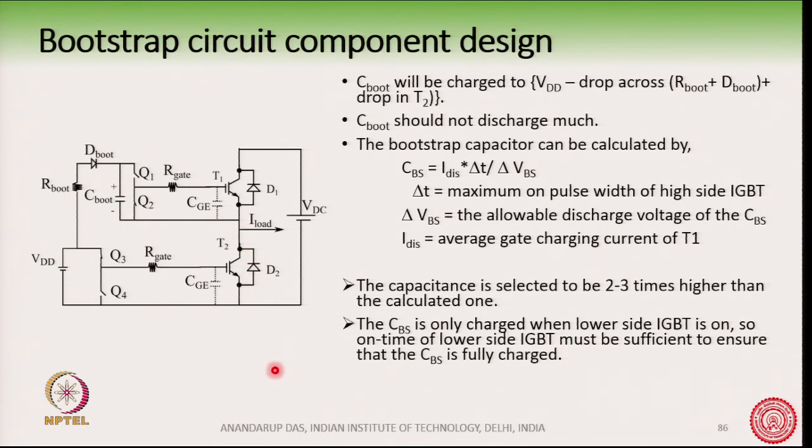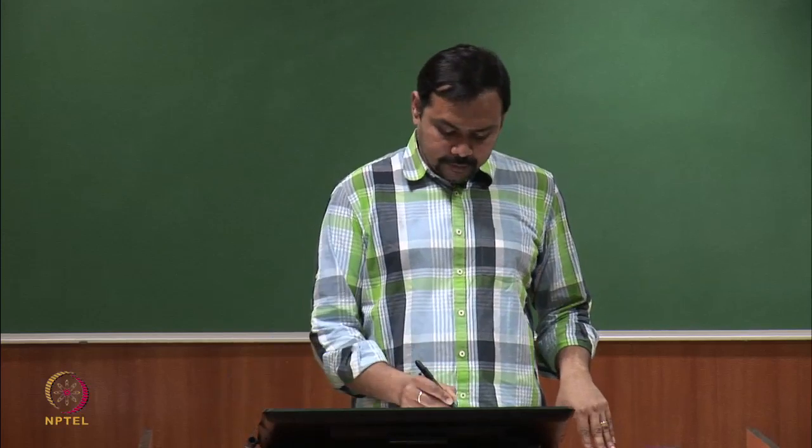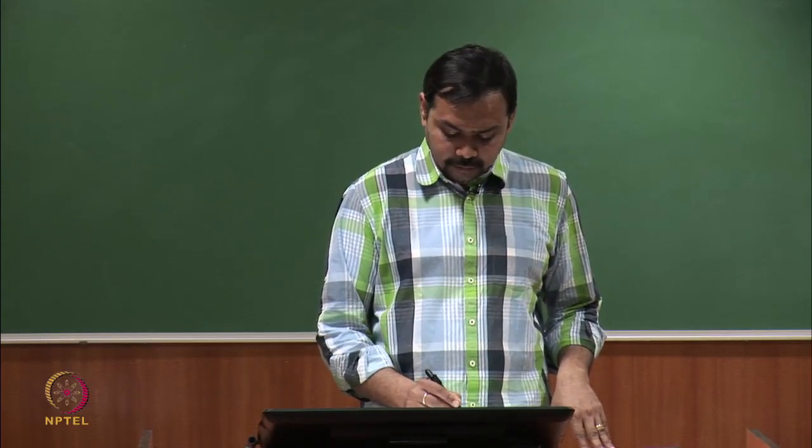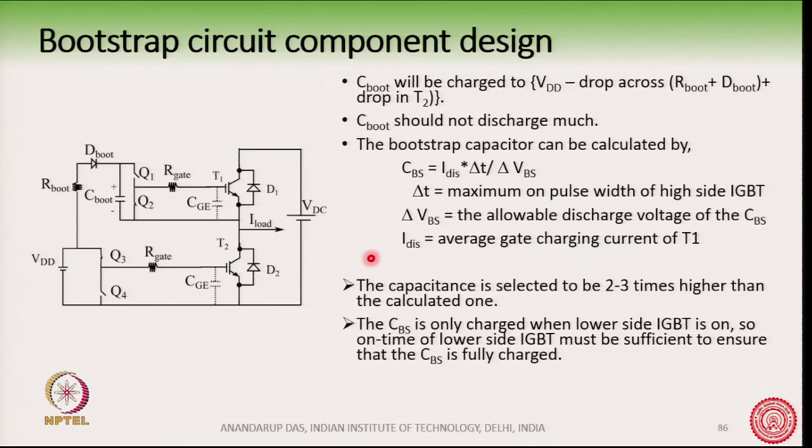In fact, for many such bootstrap circuits, the first pulse should be on the lower IGBT, because suppose when it is turning on, C boot is fully discharged.